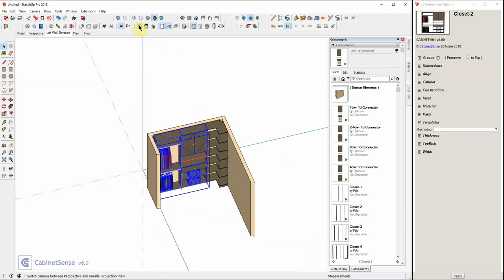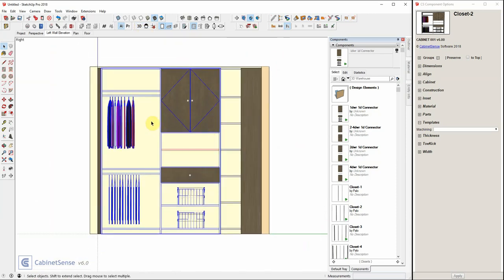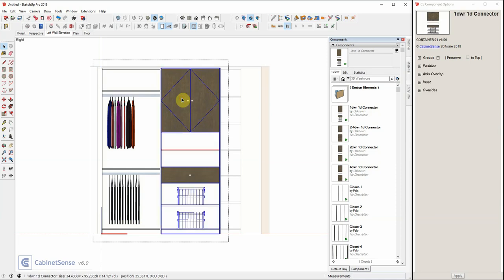I'm going to turn off 3D. I'm going to face the cabinets toward me. And now I have a view that's unobstructed and allows me to easily work with this bay on the right. I'll double click to go back into edit mode, single click to select it. And if you're looking over on the right hand side, I'm at something called a container. This was the element that I initially dragged and dropped into the right side of the two closet bay component.